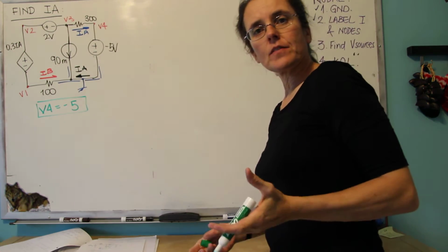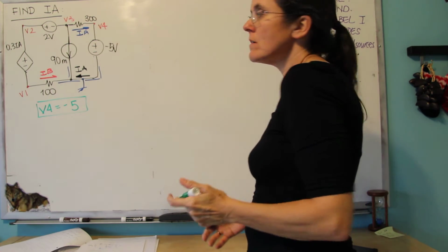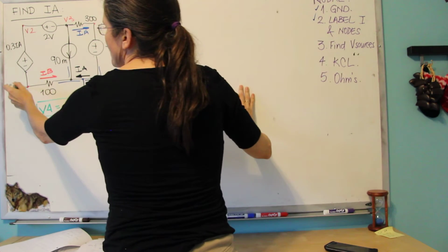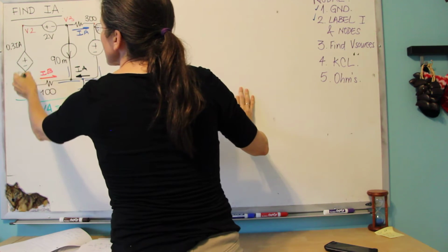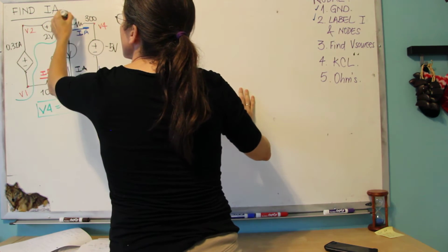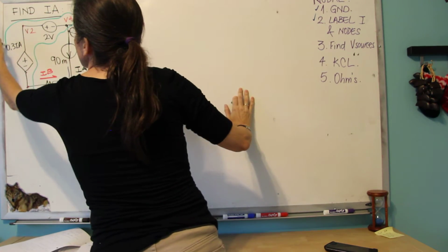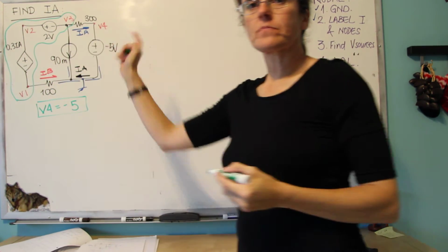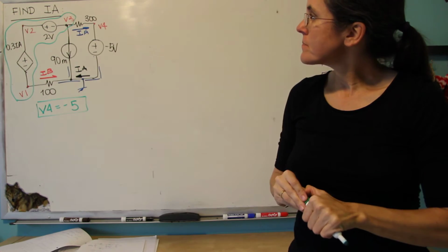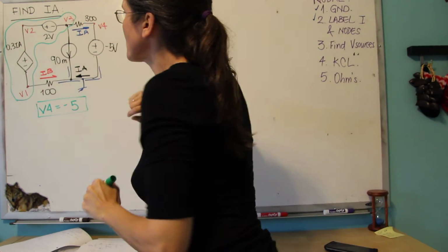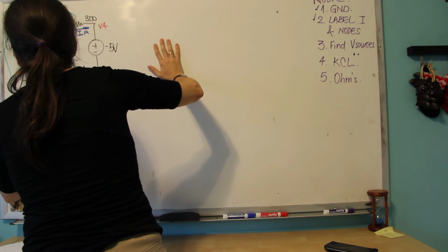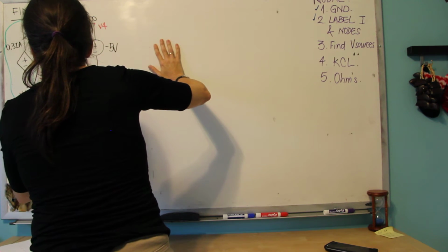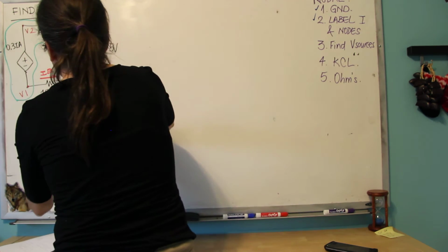And then I see other voltage sources here, which are connecting V1 to V2 and V2 to V3. So this is a supernode. And I can write equations that connect these 3 nodal voltages. So the supernode composed by V1, V2, and V3 will have the following equations.